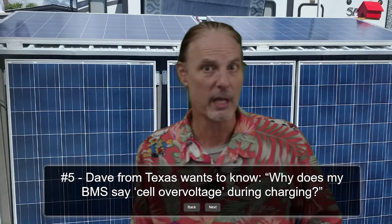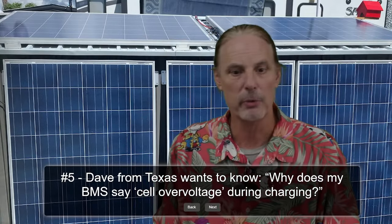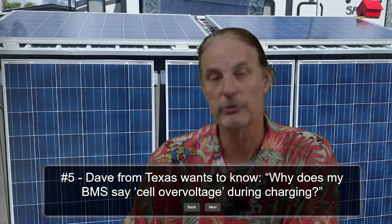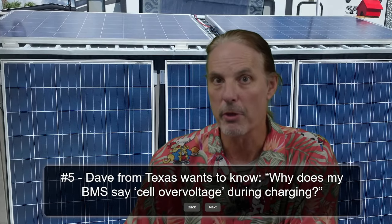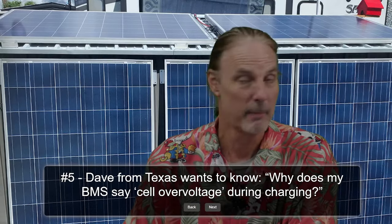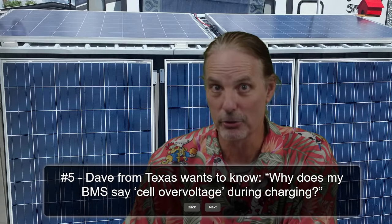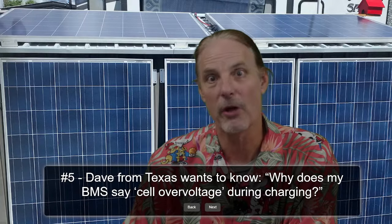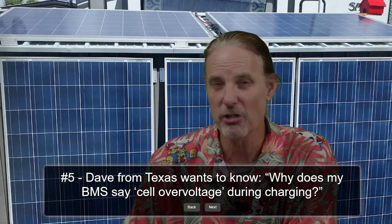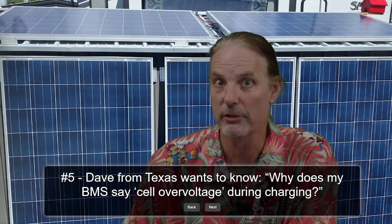Because at this point, the lowest cell in that pack that we had over there on the demo is 3.3 volts. And that means that that whole battery is going to perform at 3.3 volts capacity, not at the 3.66 volts, because the other battery cell will shut the pack down when it gets too low, and it won't be able to use all the energy stored in all the other cells. Just as charging stops when you get too high, discharge stops when one cell gets too low.